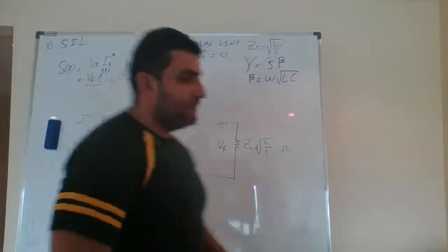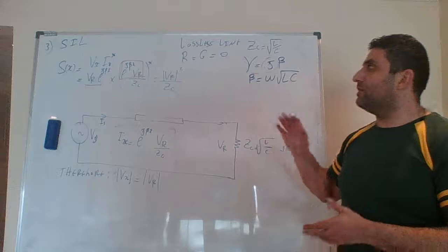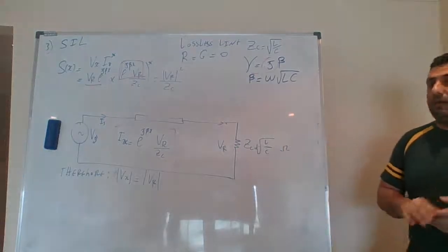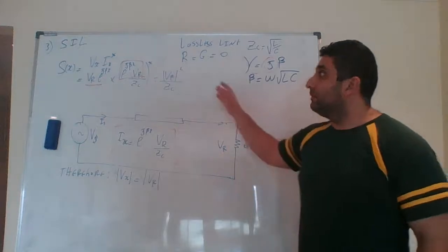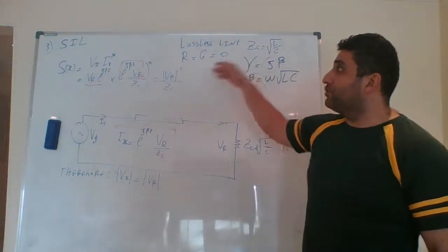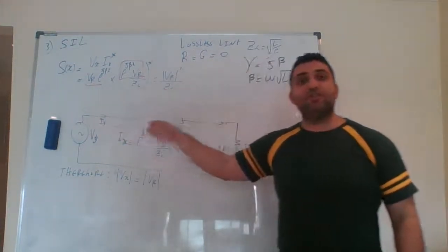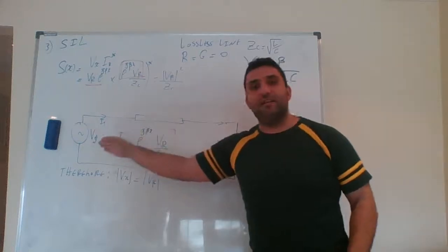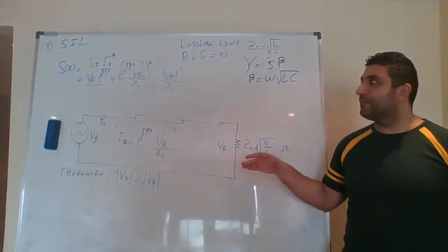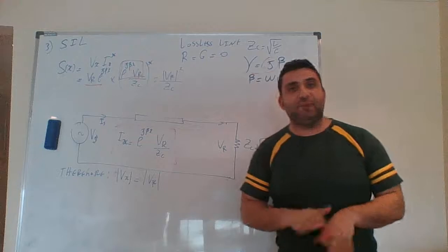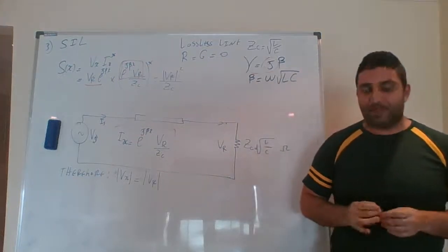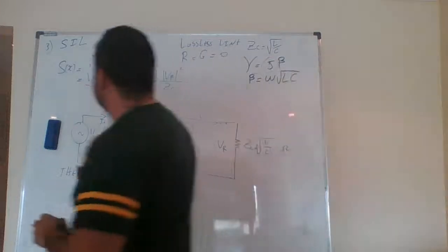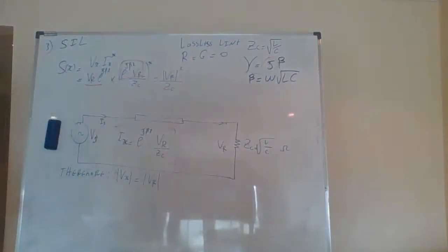Okay, guys, this is the importance of the surge impedance loading. The surge impedance loading for a lossless line shows that the power along the transmission line never changes from the sending to the receiving end, and the reactive power is zero. Is that clear? Okay.